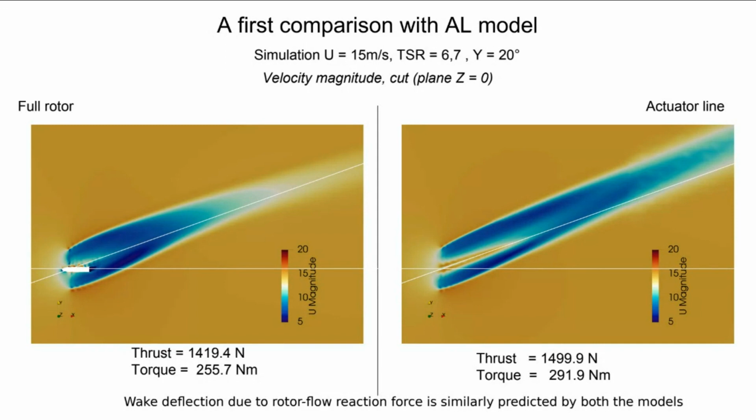And if you imagine to have another wind turbine on the line just behind the first one at a certain distance, making this one work with the misaligned wind condition can free a part of the rotor of the second turbine that we can imagine to put downstream. So also this deflection seems to be caught by the low order model. We see less diffusion of the wake for the reason I was telling before.